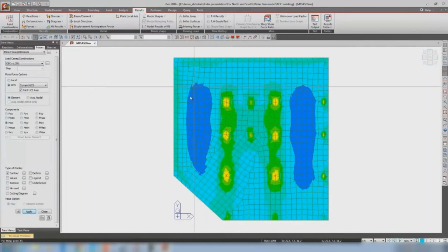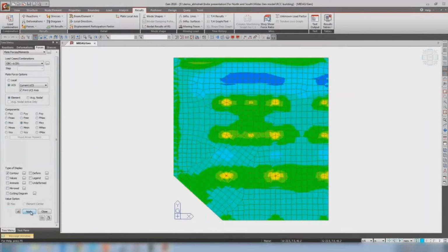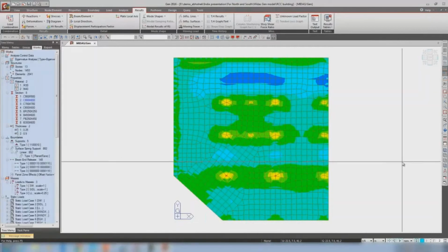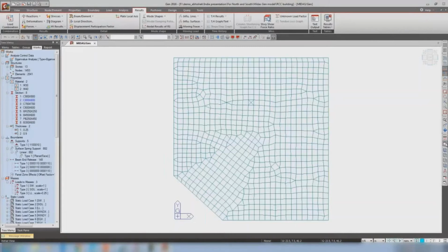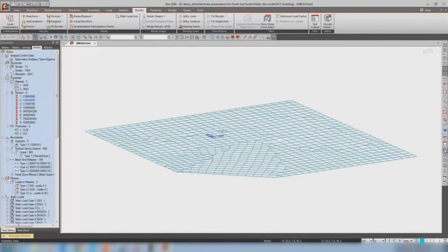Now you can see I have to put the values in the other direction. This is for Mx, meaning I have to put my X reinforcement. My diagram is vertical. Similarly for My, if I say apply, my diagram moments are horizontal, but I have to place my rebar vertically. Even by using Midas Gen, you can get the raft design and flat slab design, by area of steel as well as the rebars also. So these things are available.